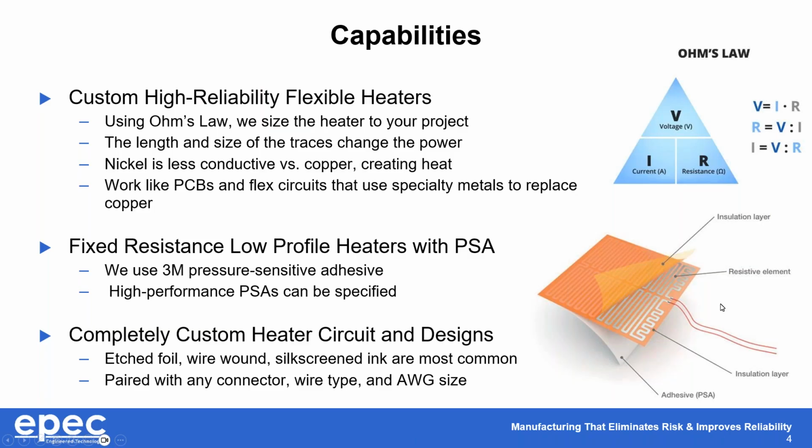Another key facet here is how to properly strain relief the wires. This is a point of failure with some designs. Every design we create has a detailed DFM, design for manufacturability, that's performed, in which we may make recommendations to the wire attachment method and any additional strain relief that would be necessary.